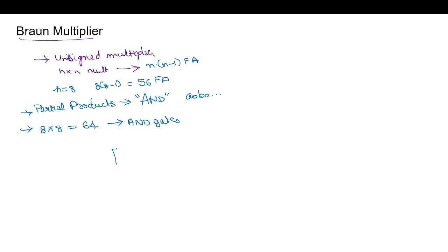If we have a block, we will get a sum after the addition. This carry is added with the next stage. So the carry signals are shifted one bit to the left and are then added to the sum bit of the first adder, and the new partial product is generated.